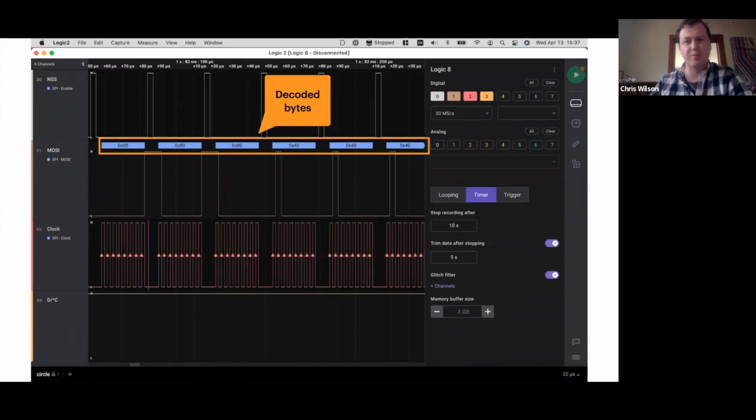And this, I'm using a device called a logic analyzer, and it basically is like, if anyone knows what an oscilloscope is, it shows different voltages over time, but this is specially designed to work with digital voltages. So that's why these lines are all very crisp.